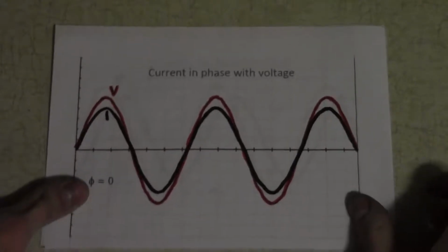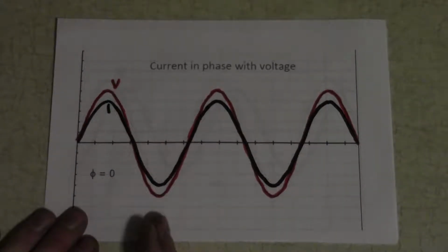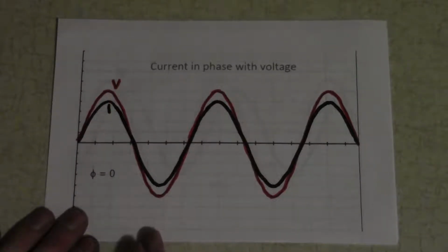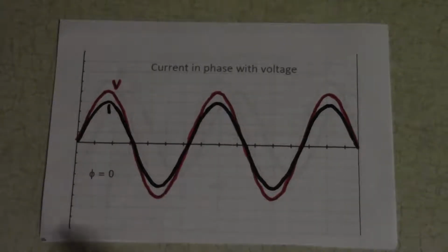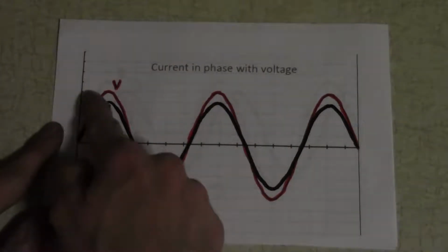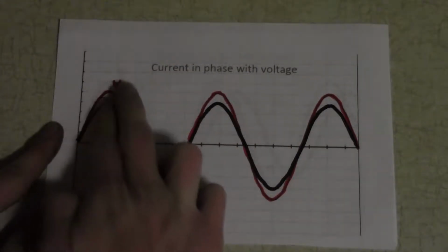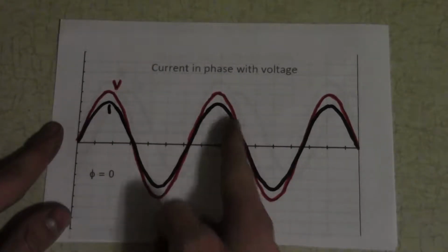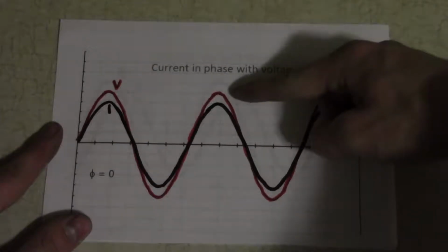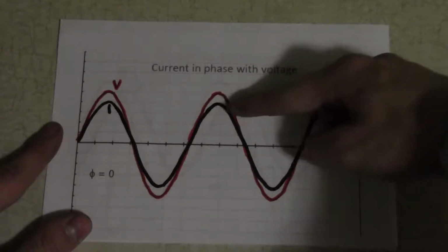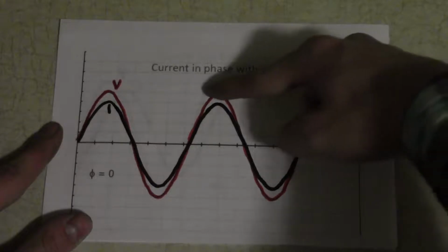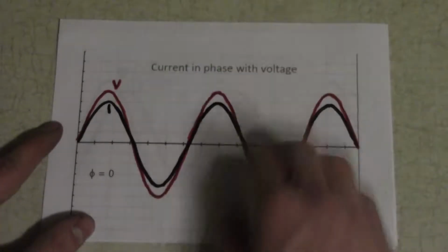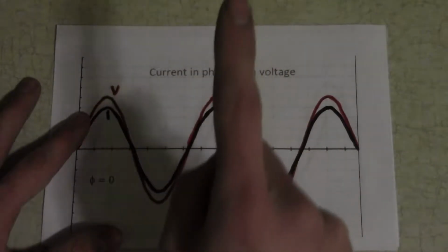Power factor, very simply, is the relationship between current and voltage. So, for example, this is a perfect resistive load. You just put some sort of shunt across your 120, and as the voltage rises, the current rises. They rise together, boom, perfectly in line. The peak voltage corresponds to the peak current. The highest point on this current curve is exactly in line with the highest point on this voltage curve. Easy. This has a power factor of 1.